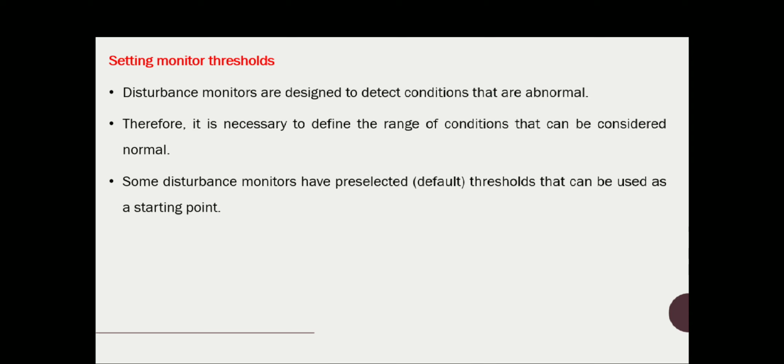So before going to monitor the power quality issues, we should collect a lot of disturbance data, and from the selected data we need to choose a threshold above which it will cause an abnormal operation of the equipment. So setting a monitoring threshold is another objective or consideration when we are planning for power quality monitoring.